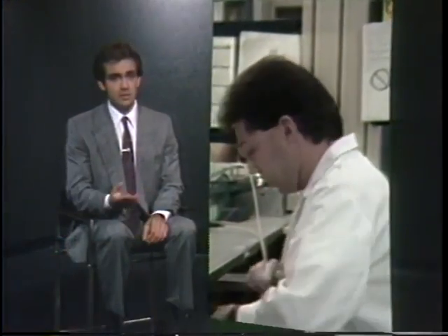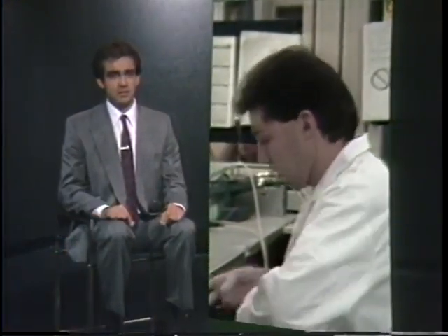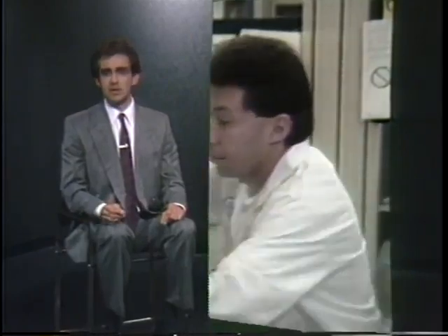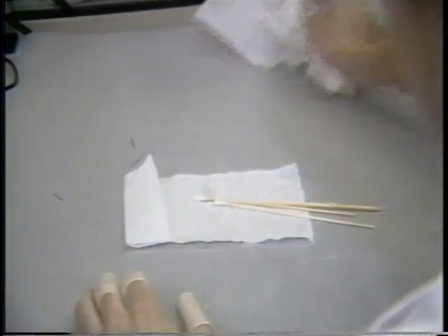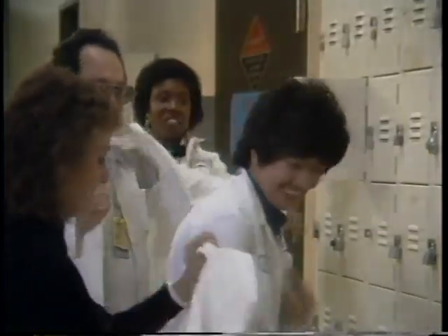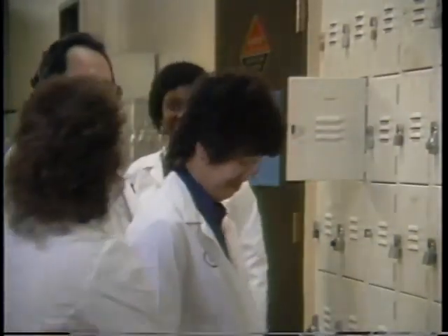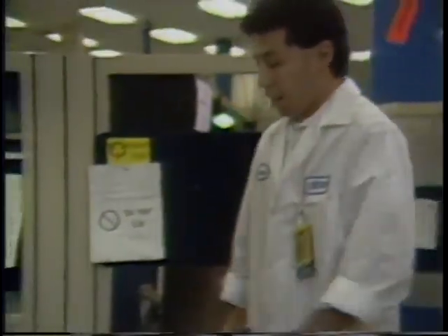ESD label. At your workstation, you have the ultimate responsibility. Make sure your workstation is free from all unnecessary materials. Many personal items carry static charge and can cause damage to electronic components. If special clothing is required, check the MPS or with your supervisor for the proper protective garment. Before beginning any job, check your workstation to make sure it has been certified.